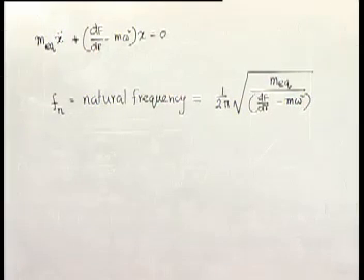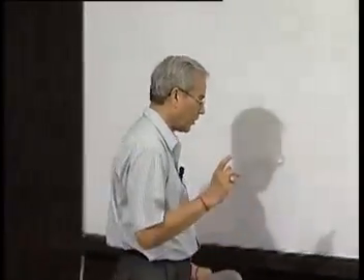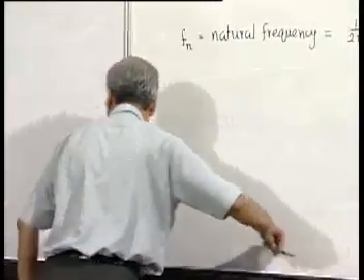that it is possible to achieve much higher sensitivity or response if we base our operation not on the change in velocity, but rate of change of velocity, that is acceleration. So, rather than waiting that velocity will change from one value to the other and basing our system on that change, a better situation we may get if we can sense the rate of change of velocity at any instant and operate our governing mechanism on that. So, I will just give one quick example of an inertia governor.